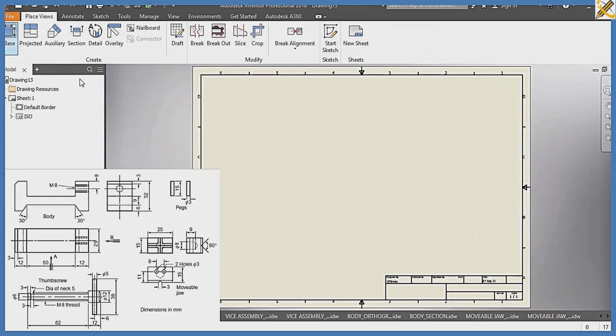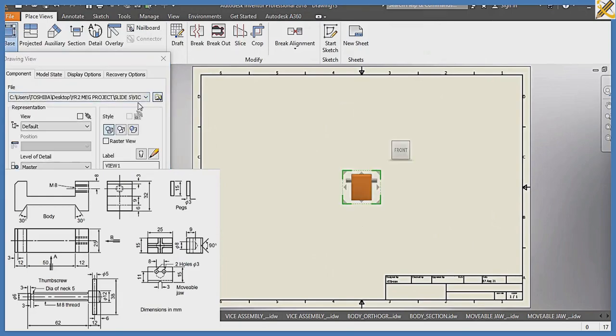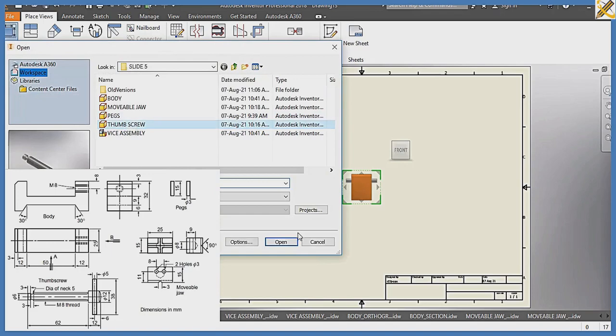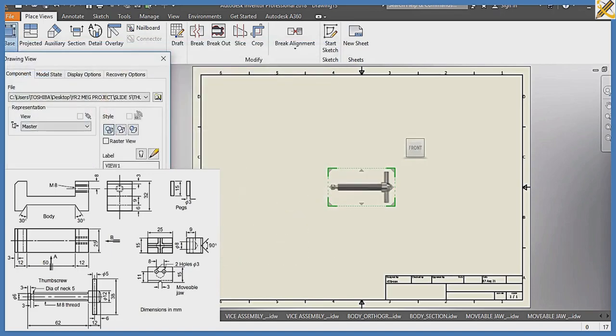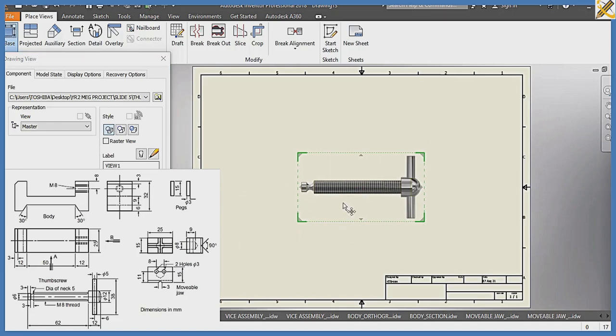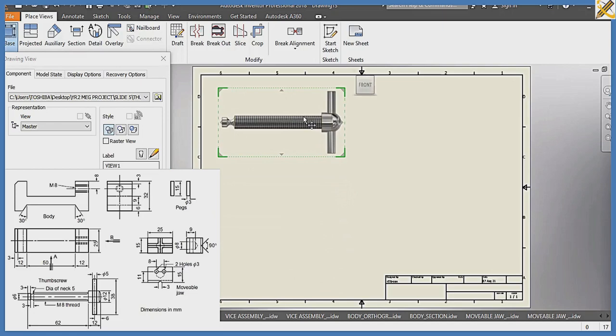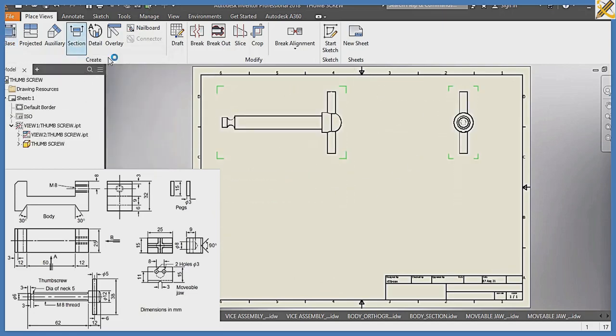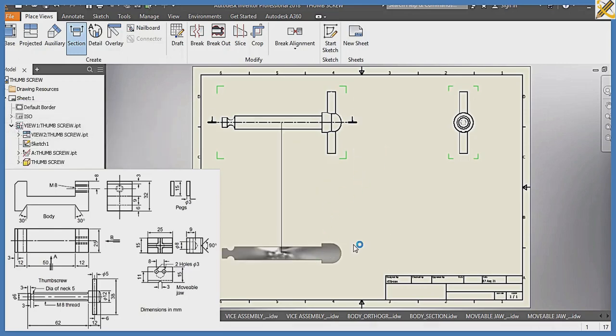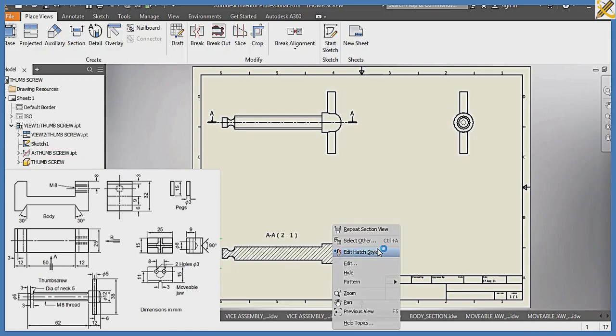After creating, I am producing the section of my last item there, which is the thumb screw. Open. So scale 2:1. Coming right here, having the end view there. Okay, section, I can as well section this here all the way here, then to the bottom in this manner. Settled. So remember we don't section both, so I'm going to hide that one.